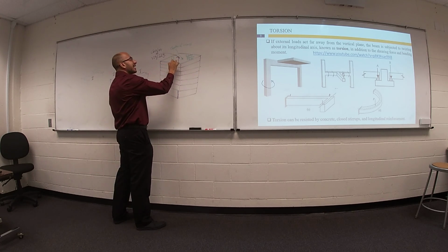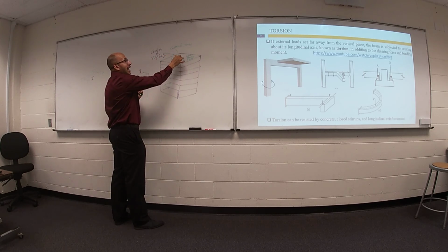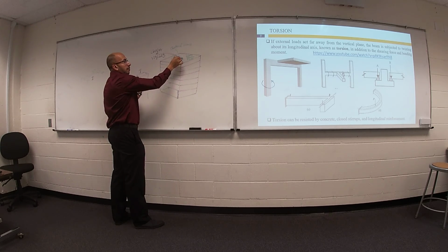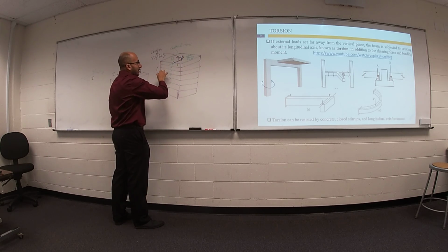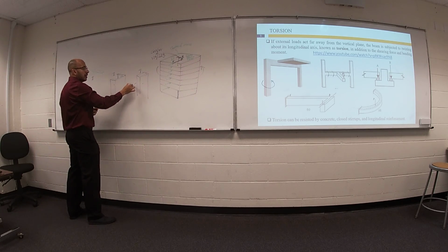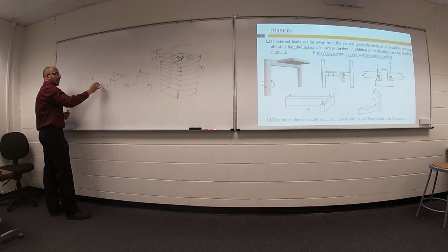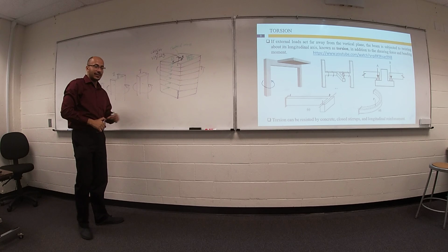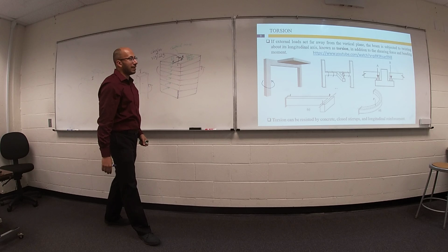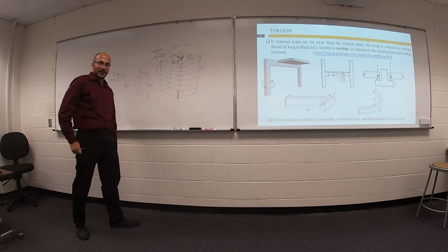Your force acts at the point of center of mass. We have eccentricity in between. If you multiply this force by this eccentricity, you can expect torsion of your building. Then your column will be under the effect of torsion. We hate this situation because torsion is a brittle failure. Suddenly, you will find your building collapse. You got it? What is the solution?